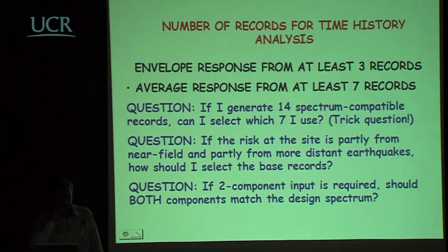So our feeling is that generally it's best to use recorded accelerograms that are manipulated by wavelet theory to match over the entire spectrum range. The disadvantage of that is that it tends to create an artificially long earthquake record. And with an artificially long earthquake record, cumulative damage may be a problem if your computer program models that, which very few of them do.